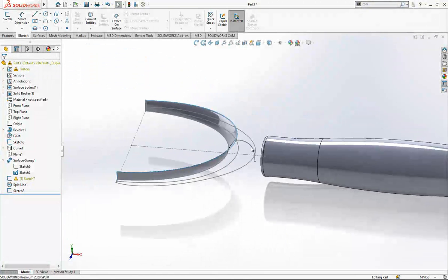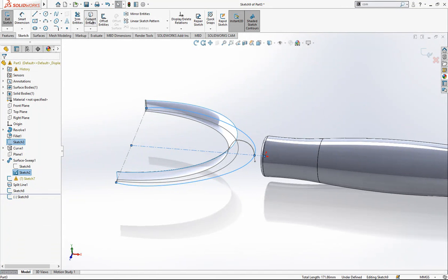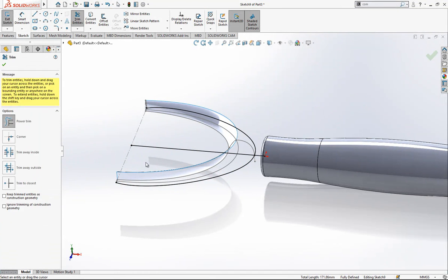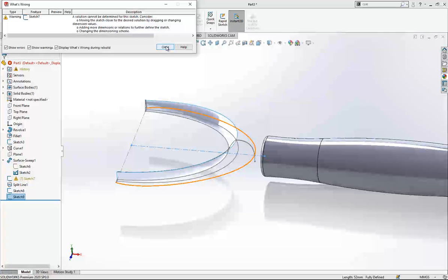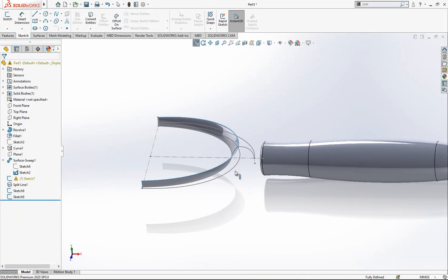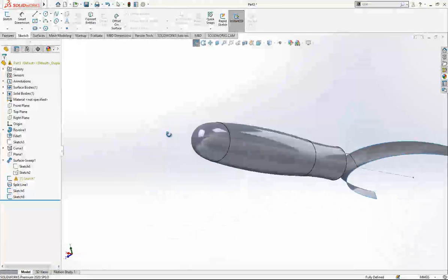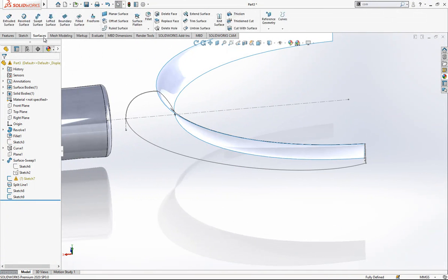And yeah, we can make a loft now, but firstly we should divide this profile into two pieces. On the top plane I'm opening a sketch and I convert this to geometry. Yes, basically now I have what I have here: starting profile, ending profile, outer and top, and then we can start the loft.